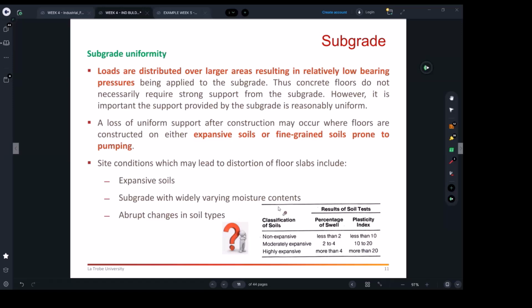There is a process geotech engineers know where construction engineers dry and compact the ground, for the first meter, to let its moisture content stabilize. Alternatively, it's advisable to remove the trees maybe 6 months before construction, so they let the ground settle by itself. There are a lot of techniques to do this, but you just need to know the main ones.